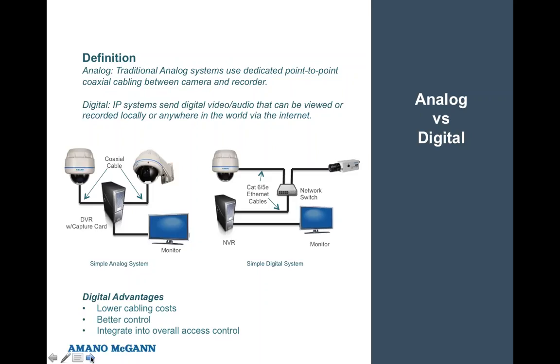So today with power over Ethernet, it's made it much simpler, and the cameras are much more efficient and cost effective. And even the doors, because we talk about the locks of the doors. That's a wiring standard, but we put some kind of adapter in place near the doors so we can backhaul it over the same digital interface, right? So that's one of the reasons that you can integrate all this, that it all can be backhauled. Right. So over every door, we put a specific controller that holds the program for that door, so that if there's a break in the communications, the door will still open and still function no matter what, even if there is no communication to it from the main controller, which is great.